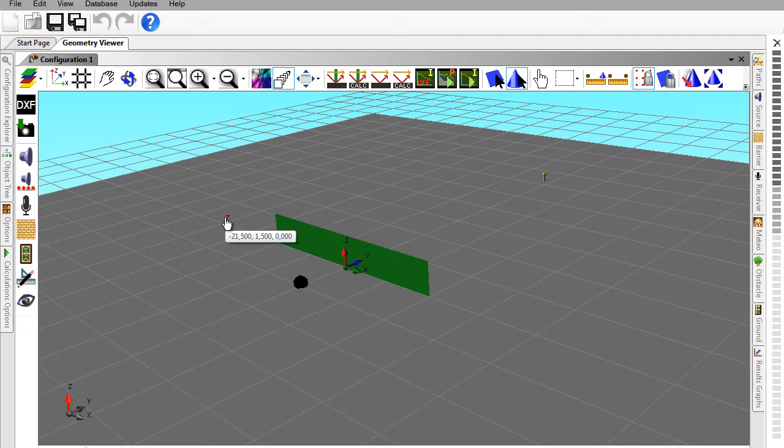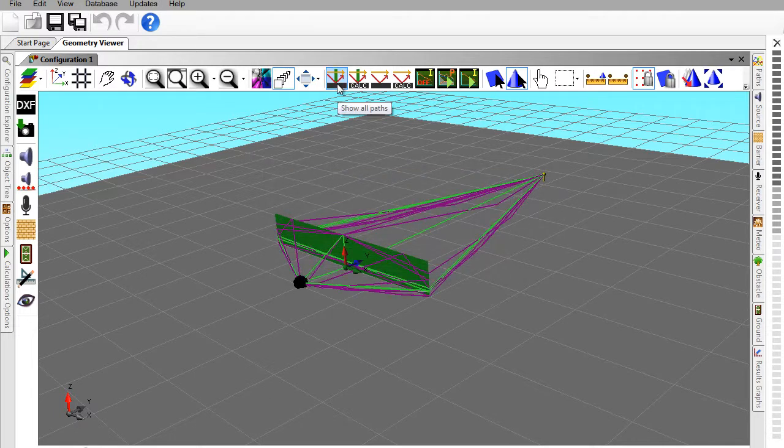Calculations in terrain are based on sound ray paths. The process is divided into two parts that combined produce the final calculation results. The first part is predicting the paths between the source and the receiver. This gives the user an indication of the route the sound is going to make to reach the point of interest, where the receiver is located. The second part uses those paths and calculates the effect on sound reaching the receiver, taking into account diffractions and reflections on objects.